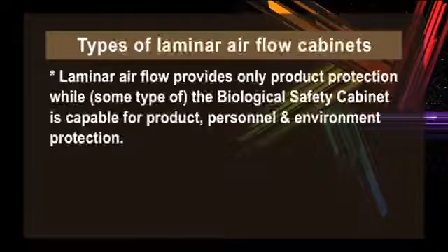Laminar airflow is not a biological safety cabinet. These two cabinets, although they do not differ in appearance, are totally different and cannot substitute each other. Laminar airflow provides only product protection, while some types of biological cabinet are capable of product, personal and environment protection.